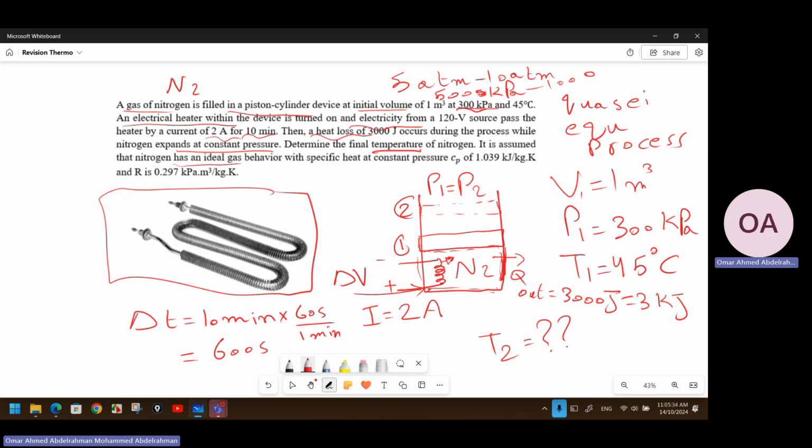So usually, in all the chapters, even in advanced thermodynamics, we will assume any gas that we have is an ideal gas in order to use the equations of the ideal gas. PV equal to RT, PV equal to mRT, like this. Okay? And the temperature, what we mean by high temperature is above freezing. Okay? So 45 degrees, 60 degrees is high temperature for us to assume that it is an ideal gas.